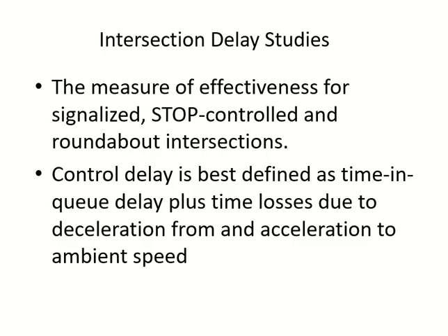Now we have discussed stop delay before. So now delay at the intersection is stop delay plus something else. We call it the control delay. So the delay which is measured at the intersection is called the control delay. Why? Because at the intersection you have a control device. That device controls how people should move, like a signal or a roundabout. These are control devices. So that's why we call the delay control delay.